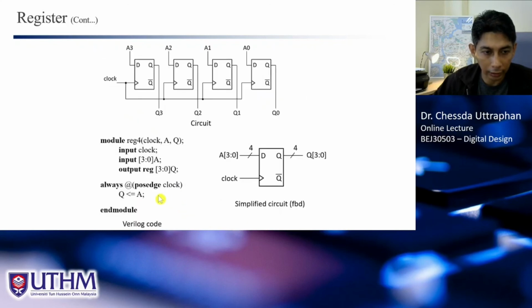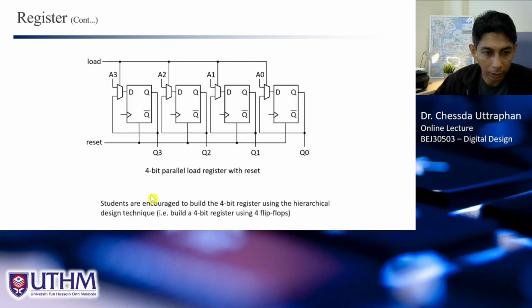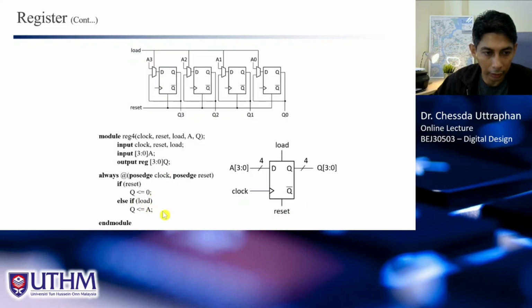This one is not hierarchical design because we define all the structure of the register here using this code only. Hierarchical means that you create one part of the register and you connect it with the other one using module instantiation. Remember?